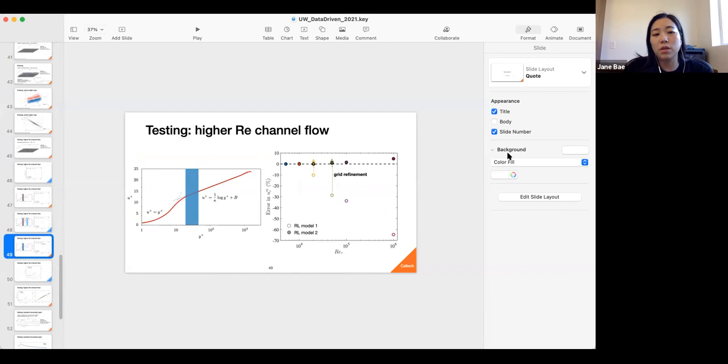So I'm keeping the streamwise and the spanwise grid resolution the same while just refining in the wall normal direction. In that case, the cost would be on the order of Reynolds number to the power 1, which is in line with what we expect from WMLES. And for the other cases, I keep the grid resolution constant even as I increase Reynolds number. So the cost is constant.